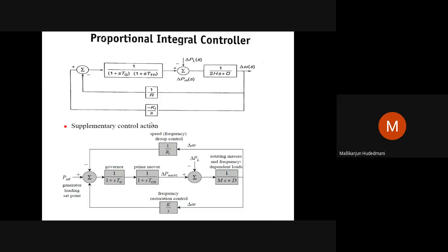Now, that was not at all sufficient. Now, I will recall back. What is ALFC? ALFC is an automatic load frequency controller. It has to see to it that as and when there is a change in load, and frequency drops, to supplement the drop in frequency, it has to increase the mechanical input to the turbine. As well, it should see to it that the RPM of the turbine is managed properly. That is supplementing the mechanical input, the primary part of the ALFC closed loop.